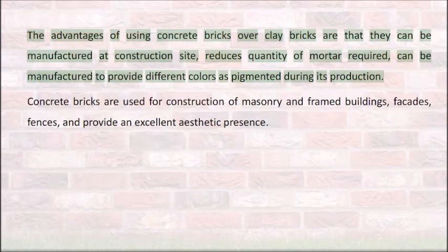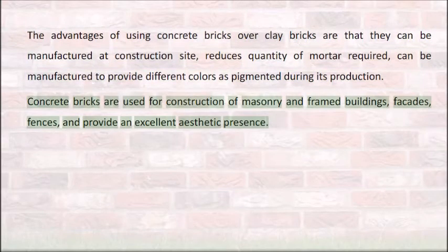The advantages of using concrete bricks over clay bricks are that they can be manufactured at the construction site, reduce the quantity of mortar required, and can be manufactured to provide different colors as pigmented during production. Concrete bricks are used for construction of masonry and framed buildings, facades, fences, and provide an excellent aesthetic presence.